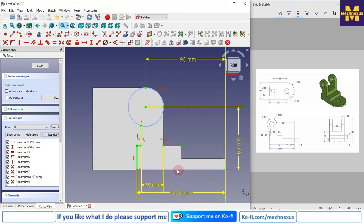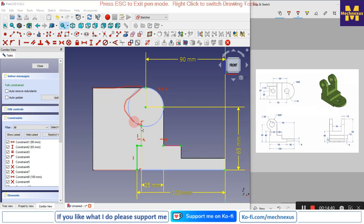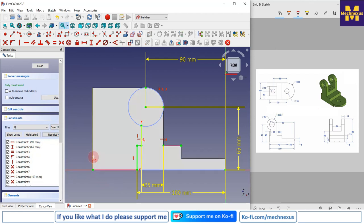Okay, now we also make it a construction because we want to remove the material at this portion. That's why we have kept it as a construction. Now I will project this edge and this edge and draw a 3-point arc and close our profile. So for this I will click on project geometry. I will project this one, this one and this one.